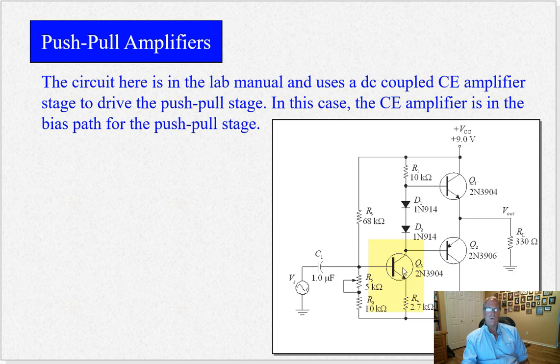So this transistor is turned on slightly or off slightly depending on the setting of this potentiometer, and that's going to replace that resistor that used to be another 10K down here, maybe. So it's not going to be 10K anymore. It's going to be something other than 10K, maybe 10.5K or maybe 9.5K, in order to compensate for the differences in these bias voltages.